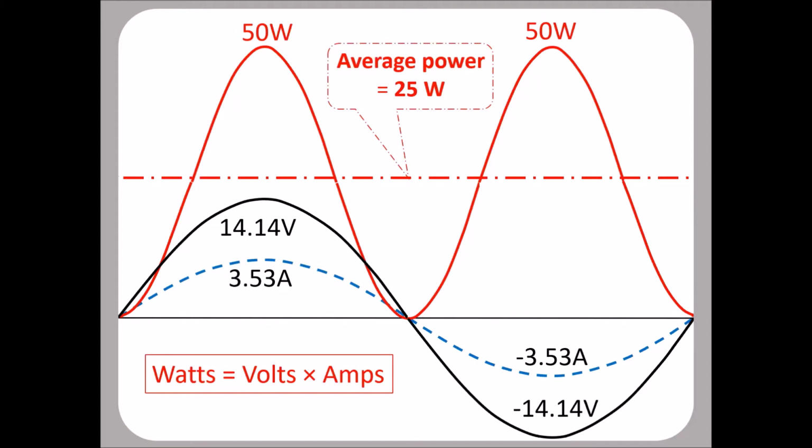Now, if you're thinking, well, does that mean that inside the bulb, the filament is alternating between 50 watts and zero, so it's glowing brightly and less brightly? The answer is yes. It's flickering, but it's not. If you look at the times involved, we're on a 50 cycles per second supply. So that peak going up to 50 and back to zero is 1/100th of a second.